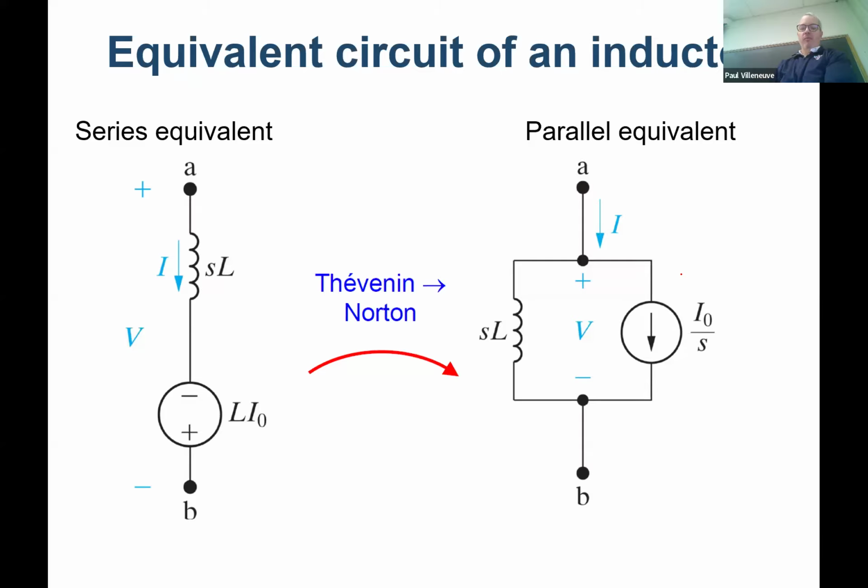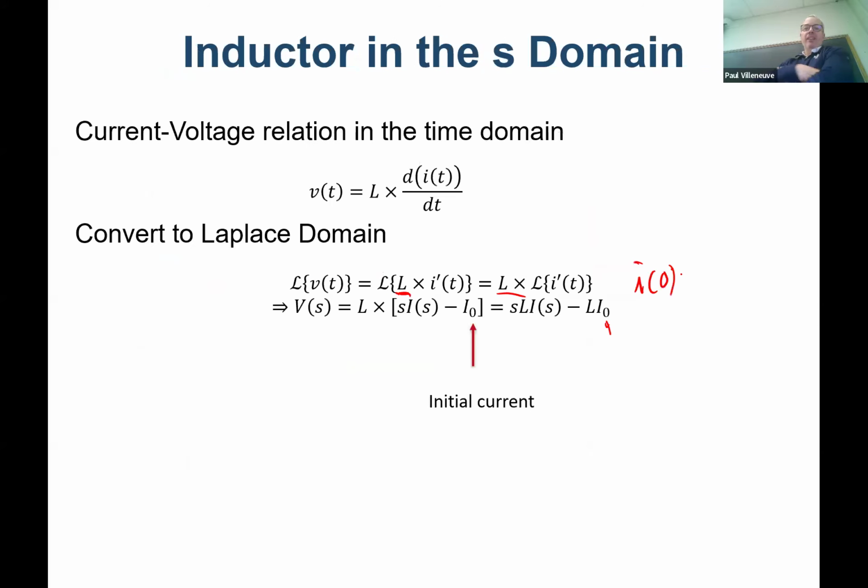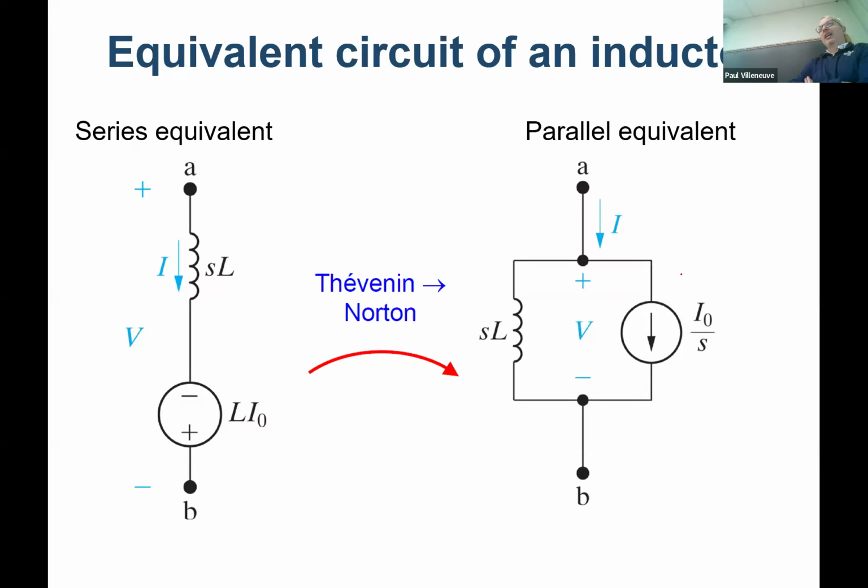But I could have written the initial equation over here, right? Instead of saying L dI/dt, I could have used the integral, right? I could have used the voltage initial condition. But why did I use I and V? Henry's got it. Can the current instantaneously change in an inductor? No. So if I use the initial condition of current, all I need to do is find the current.